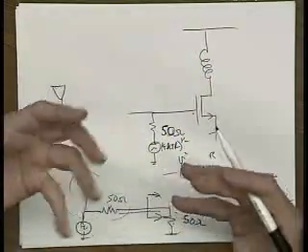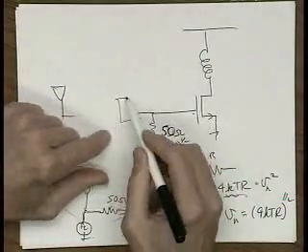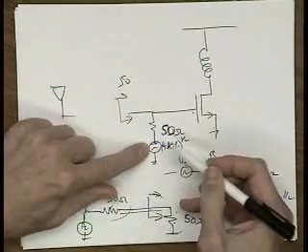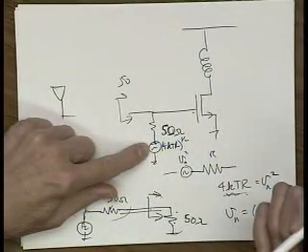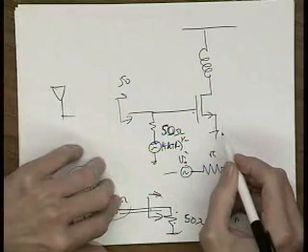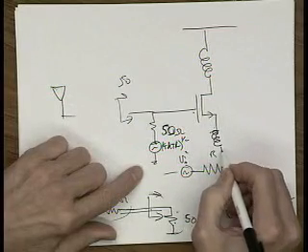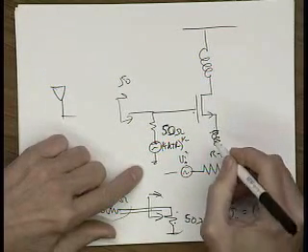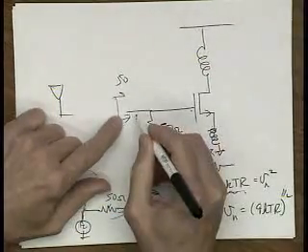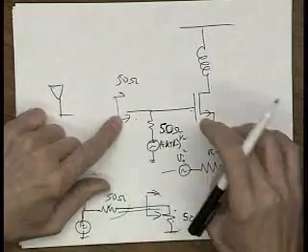Well, I can get rid of that. I don't have to do that. I can make this look like 50 ohms without actually adding a resistor. And that's your project, your homework actually, to show you how to do that. Effectively, and it's pretty interesting, I don't know who figured it out originally, but it turns out if you put an inductor down in the source, this can look like 50 ohms, a real resistance, at the resonant frequency of this circuit.